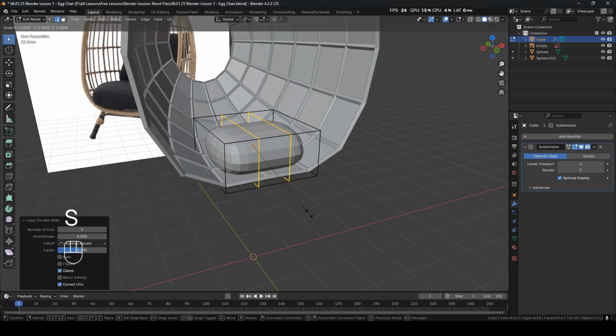We're then going to press S to scale and X along the X axis. As you can see, the scaling, grabbing, and rotating in object mode or edit mode will always be the same. So once you've got those three combinations combined with X, Y, and Z, there are a lot of things you can manipulate and edit and build any asset you desire.